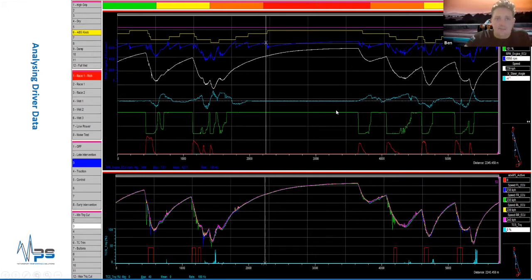Unfortunately, this Bentley is littered with sensors, so I've got all the luxuries as well. If you see the next sheet, it's a duplication of the type of graph. There's another time distance graph which I'll talk about shortly, but this time it's filled with just wheel speed sensors. You'll see I've got each corner overlaid on top of each other, so it makes it really easy for me to see when a wheel locks up, for example like this green one here, or if you're struggling for traction, like you see the pink is going faster than the blue down here.